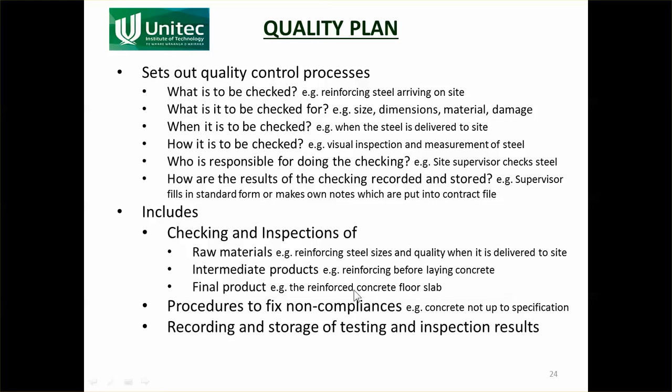You know, is it the right level? Is it the right thickness? Is it the right concrete? And if something doesn't come up to scratch, you'll also figure out what you're going to do about it. Not just we'll fix it, but how do I make sure that it doesn't happen again. So it might be that the reinforcing steel wasn't at the right cover because the people that put it in weren't informed properly. So you think, okay, well, we're going to make sure these guys get drawings next time.